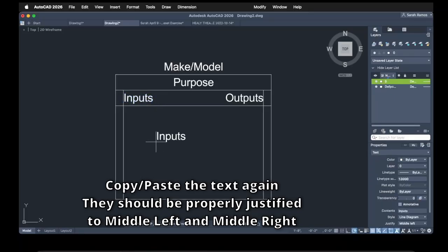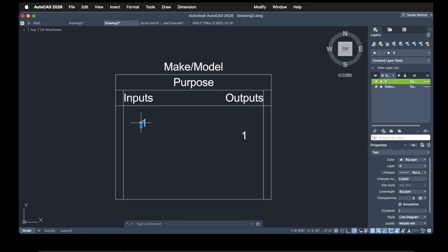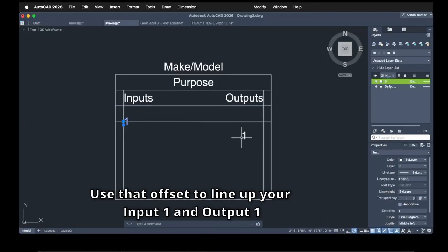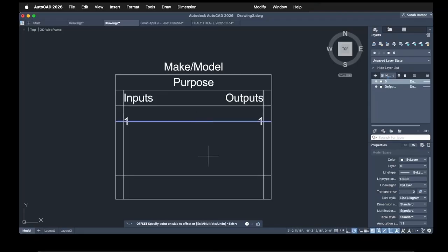This new line will be for my input and output labels, as in input channel 1 or main left out. Depends on your equipment and what they call it and what you need to use. Let's add a channel 2, and for reasons of spacing that I have predetermined, let's offset this reference line down by a value of 7 inches.